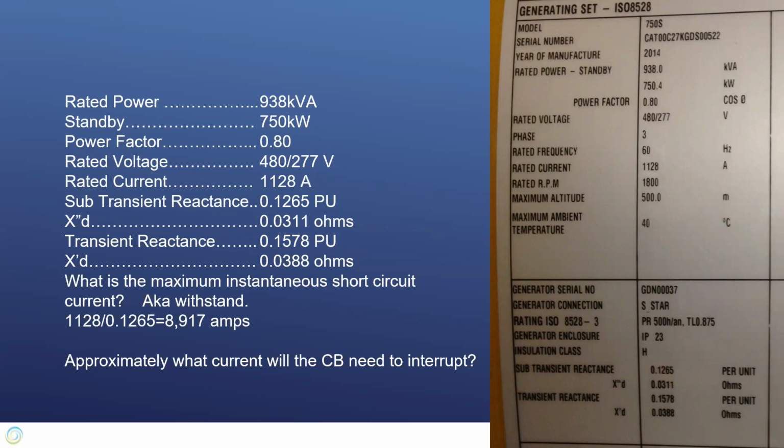How long does it take, anybody, how long does it take for a circuit breaker typically to detect a fault and open its contacts? Anybody know? Detect a fault, trip the operating linkage, collapse the link, and open the breaker. Anybody know what that time is? You actually buy them this way. Less than 3 cycles. Very good. Exactly. 3 cycles. You can buy 5 cycle breakers too, but 3 cycles is a typical value. And 3 cycles is the more difficult value to do.